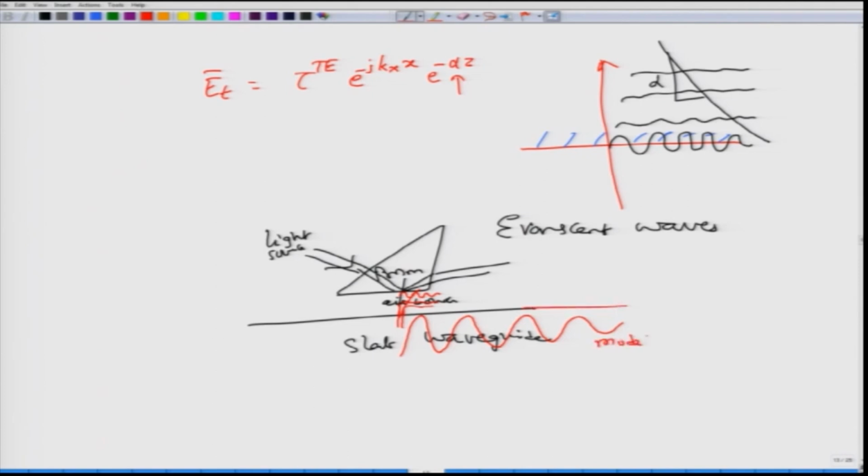So, it is just used to excite the mode inside a slab waveguide, and this form of coupling is known as prism coupling, which was very popular, and even now is quite popular to excite light into waveguides. So, the light that is being excited in the waveguide is actually in the form of this evanescent wave. Although we can show that the evanescent wave does not really carry any power in the direction perpendicular to the interface, it still can excite waves because it does not really go off to 0. So, the wave will not go off to 0.